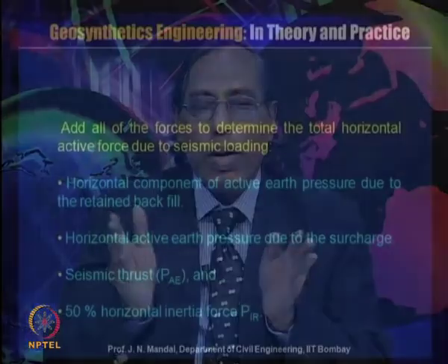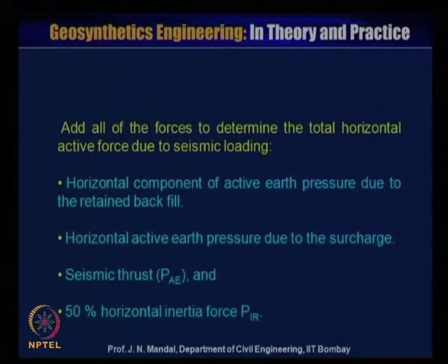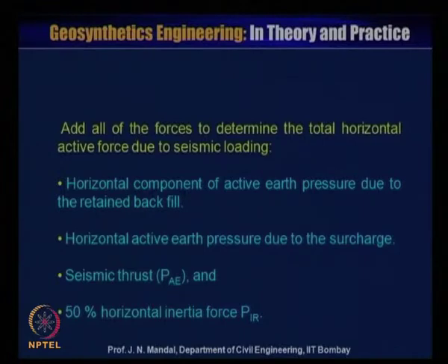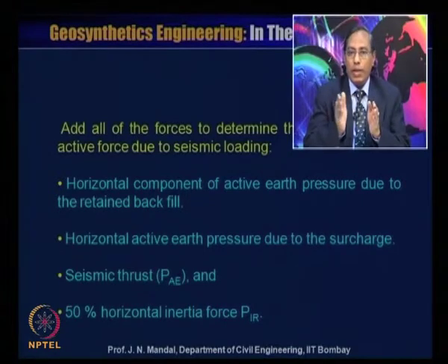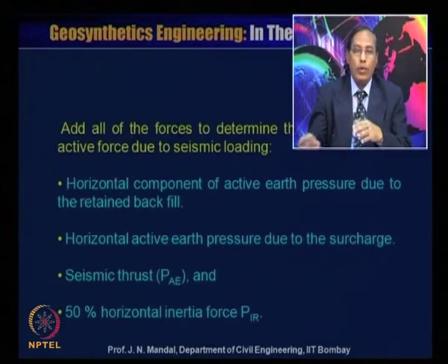So, you add all the forces to determine the total horizontal active force due to the seismic loading. That means the horizontal component of the active earth pressure due to the retained backfill soil, the horizontal active earth pressure due to the surcharge, and the seismic thrust, that is PAE. And as I mentioned, 50% of the horizontal inertia force PIR is also taken into consideration. So all the forces you have to take into consideration.